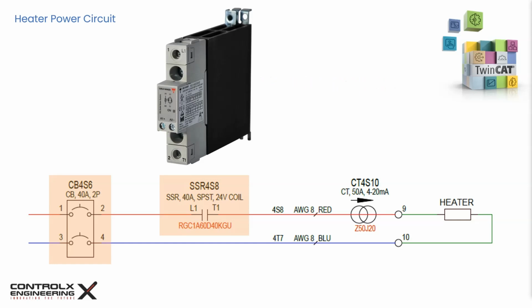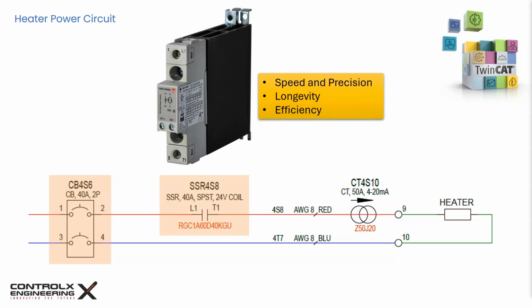SSRs play a crucial role in implementing PWM for heaters. Unlike mechanical relays, solid-state relays are electronic switching devices that have no moving parts. This makes them faster, more durable, and silent, perfect for the rapid on-off switching required in PWM control. They can handle high switching cycles without wear and tear, ensuring long-term reliability. Solid-state relays are fast and precise.